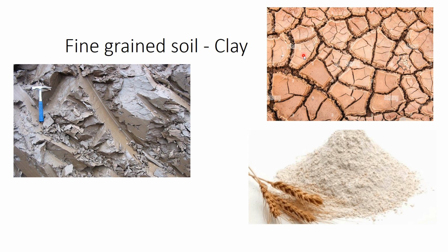When we have it in our roads, if you're going to compact, and the water becomes higher than required, it will start sticking to the rollers, and we will not be able to compact the roads. So we have to be very sure about the water content of the soil when it comes to clay or any material. To keep it in mind in an easy manner, I said the behavior of clay will be similar to wheat flour, where it absorbs water well, and it sticks to our plates when the water is very high.